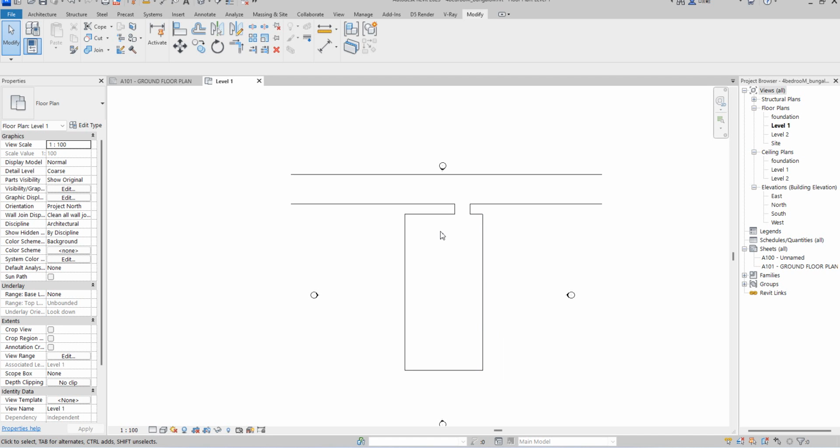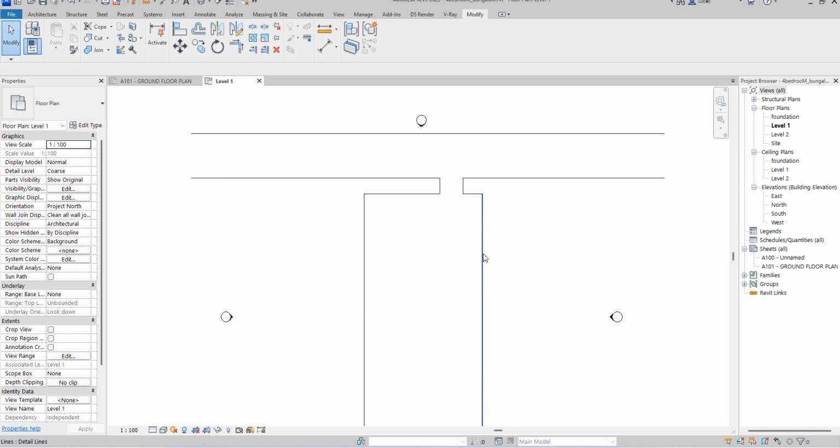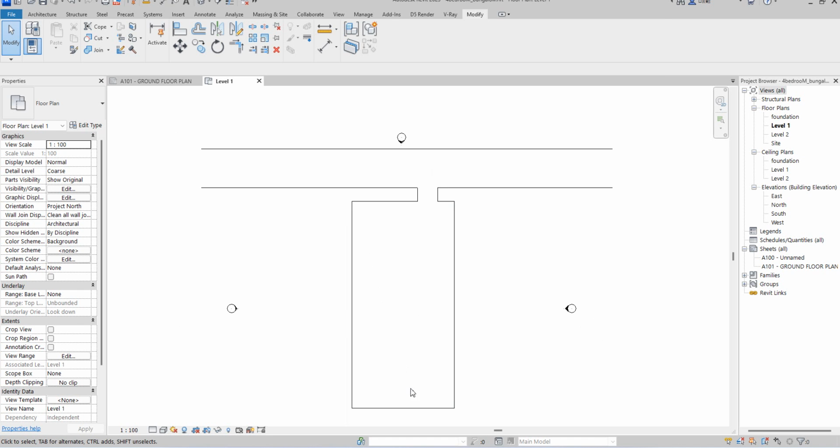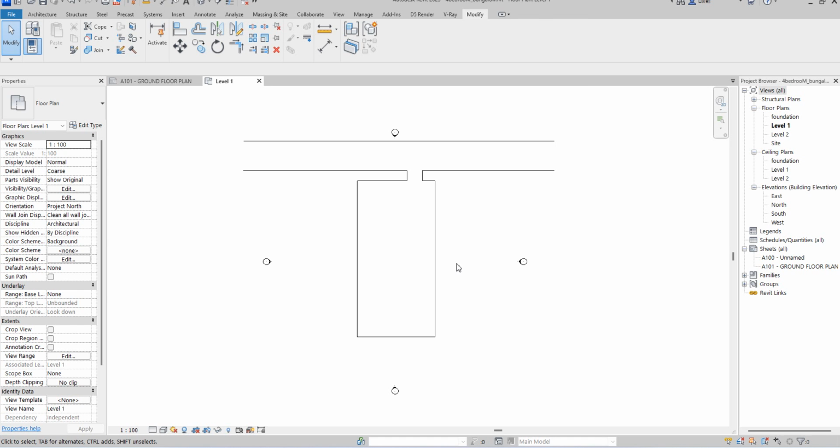So what I want to do now is to make setback, because every locality has its own setback rules. So I just want to use a standard which Lagos is specific about. So now I want to do that by saying offset. So I'm going to use 3000 millimeter for the offset. So whatever remains, I'm going to manage it to do my design.